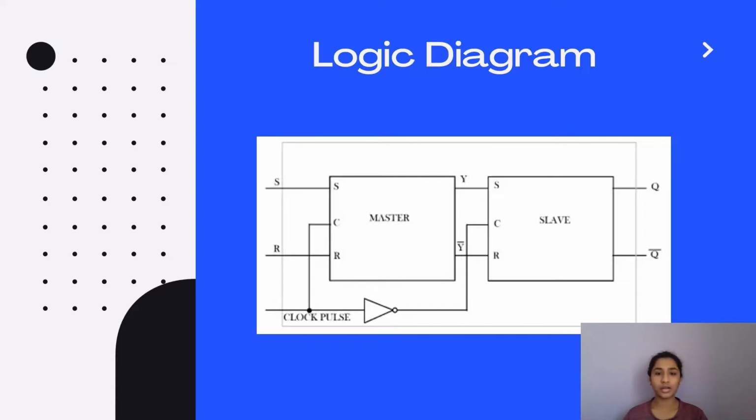So whenever the master receives a clock pulse of 1, at the same instant the clock pulse that goes to the slave will be 0, which means that at a particular instant the master is active, but the slave remains inactive. In the other case, when the clock pulse that goes to the master is 0, the master is inactive, and at that same instant the clock pulse that goes to the slave will be 1, which means the slave will be active. So at a given point of time, it's either the master or the slave that will be active and not both.